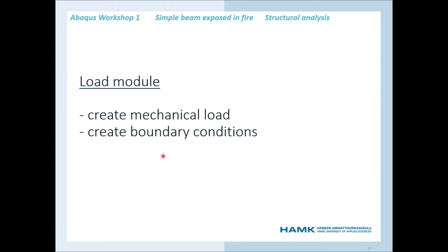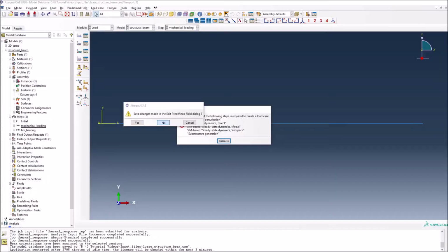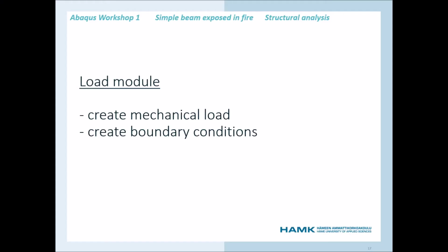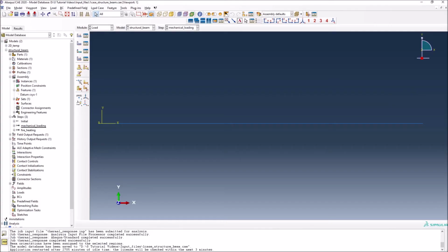All right, so let's start first creating mechanical load, and then boundary conditions. So let's move to Abaqus now. In Abaqus, we are now in the load module, and then we have the create load option here.